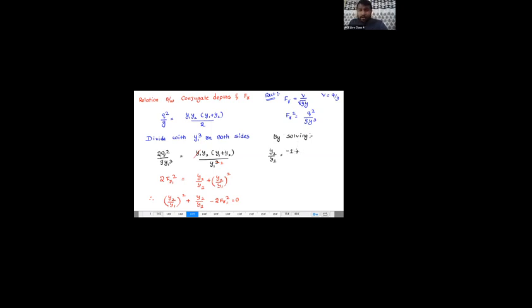Plus or minus. So I don't go with minus because if I take minus, the total value is negative. I'll go with plus root of b square. What is b value here? 1. B square, 1 square, 1, minus 4ac, minus 4 into a 1, and what is c? Minus 2 Fr1 square. Minus of minus plus, 4 into 2, 8 Fr1 square, by 2 into 1, 2. So what is the final answer? Minus 1 plus root of 1 plus 8 Fr1 square by 2. This is the final answer.